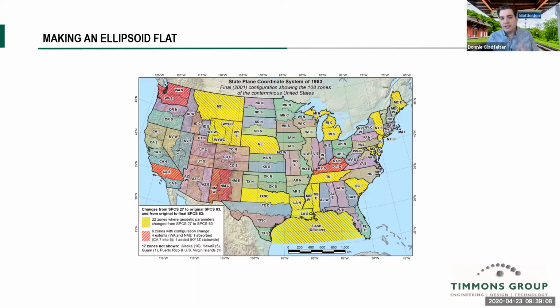And what this allows us to do is to slice up the Earth into small enough pieces that the tolerance or the curvature is within an acceptable tolerance. And so depending on where a project is, it will be projected to one of these coordinates. And this is what we refer to as real world coordinates. And we typically express this in a relationship of northing and easting to get the precise location on Earth. So this is how Civil 3D and its projects are going to be set up.